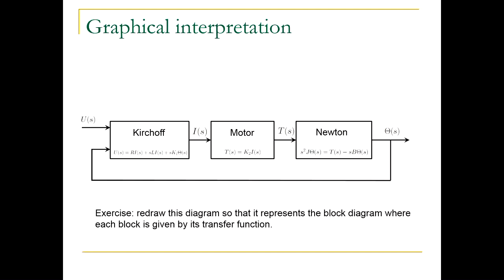This is not a block diagram yet. It's just a diagram that basically says, well, look, if I think about the torque as input to the Newton equation, the output, this torque, would cause the thing to move. So shaft angle would change. But then shaft angle does affect Kirchhoff's law through back electromotive force. We said that back electromotive force is proportional to theta dot. That's how this shaft velocity goes back and affects our Kirchhoff's law.